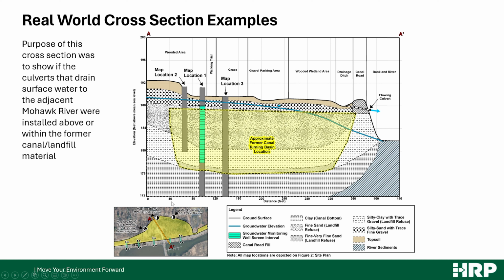We also had very limited sampling opportunities in this area of the site. We know that there's a history of buried drums, and we did not want to hit them when we were drilling. And there's no room to drill on the other side of the road. So what we used were aerial photos to show that this entire area was at one point completely filled with water as part of the canal. So it would have a consistent geology, at least during that period. And then the landfilling was done in this section of the site roughly at the same time. So we made an assumption that the lithology would be consistent throughout this area of the site. If we go back and collect additional samples and we find that there's a difference in the lithology in portions of the site that we previously didn't investigate, we'll go back and update the cross-section to reflect those new data points.